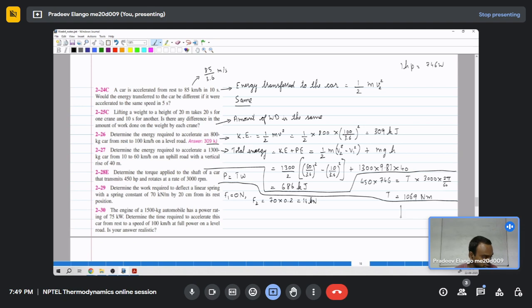So that means in force and distance we have initially 0 distance and 0 Newton force, and then it linearly increases to 14 kilonewtons, and the distance is 0.2 meters. Now the work done is the force into distance, or in the case where the force is varying, we have to consider the area under this curve.